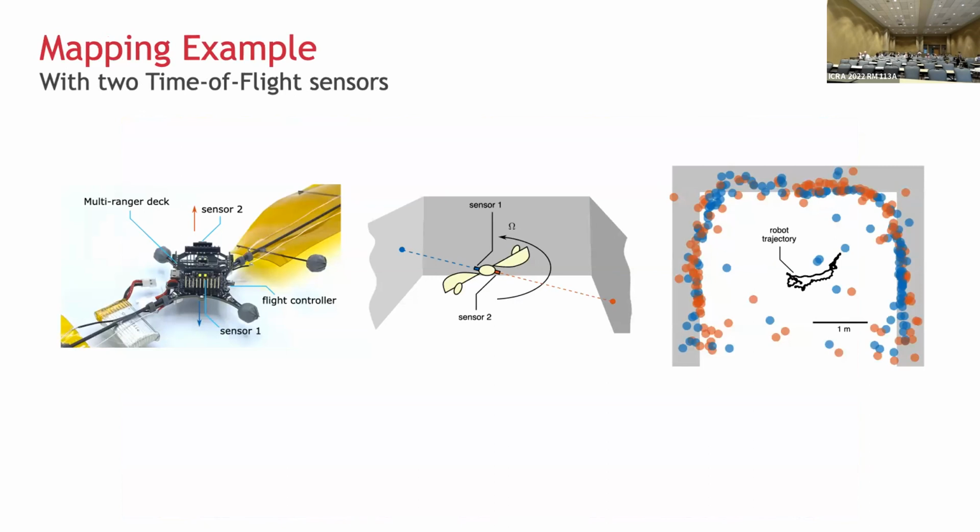So the rotation, though, I always get asked the question. If the robot keeps rotating, then how is that going to be useful, right? Thinking outside of the box, you can also see that, for example, LiDAR sensors already work by rotation. So if you just put sensors, for example time-of-flight sensors, onto the robot that keeps rotating, then you can construct a map of the surroundings directly.